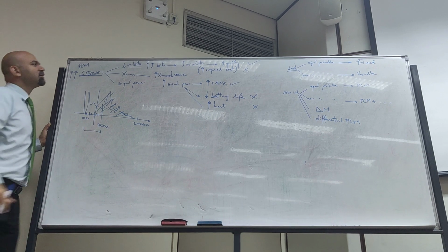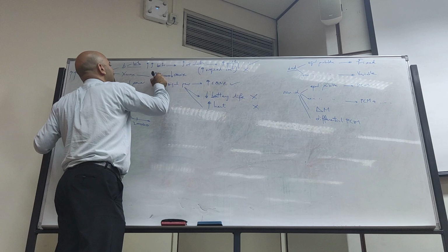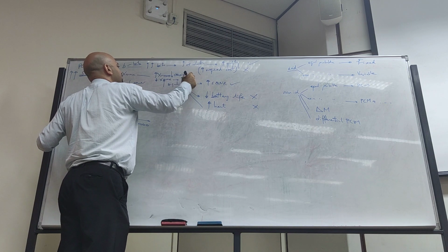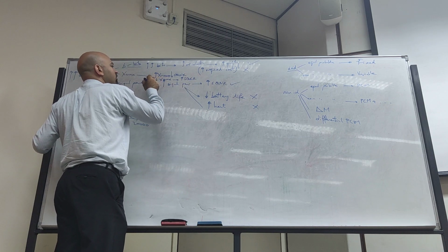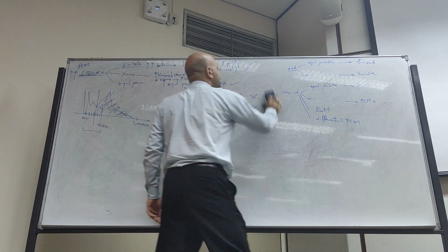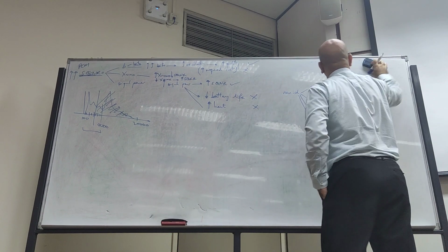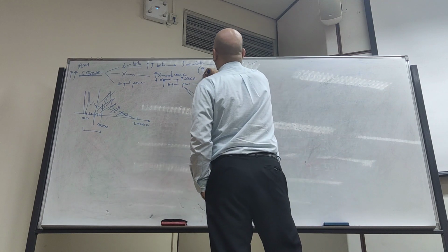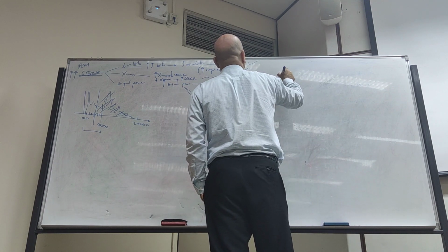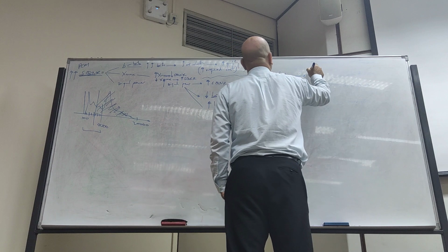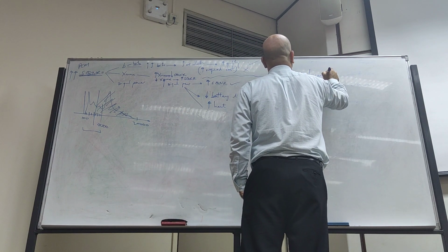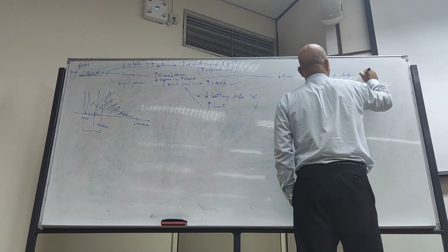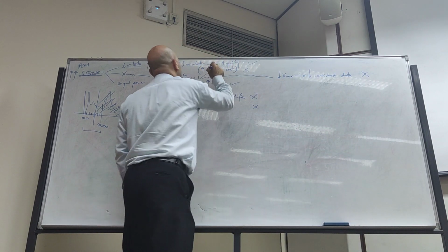Do you want to add it? So here, whenever you decrease the X max, you will increase the SQNR. It's written here, and this is good. But also, whenever you decrease the X max, you will decrease the considered data. So here you have a loss of that. This is bad. This is good.